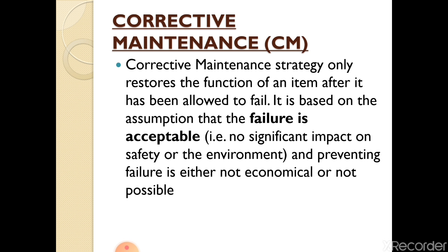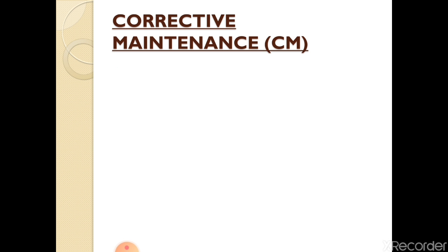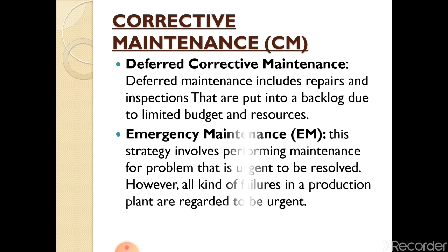The decision about how far to go with the repair ranges from a band-aid and duct tape fix to a complete overhaul. Some parts can be replaced early to extend the time until the next repair is required. So these are the objectives of corrective maintenance, or breakdown maintenance. Under breakdown maintenance, we again have two divisions. One is deferred maintenance. Second is emergency maintenance.